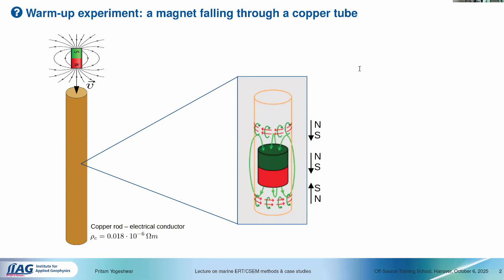So that is coupled to an electric field. Then along this ring current, you have again a magnetic field circulating around the ring current. And this magnetic field, if you look from the top, the direction of the field lines are like this, but the magnetic field lines of the permanent magnet are like this. And if you look down here, the magnetic field lines below from the ring current are reversed. So here, because it's north-south, north-south, it holds the magnet up, it pulls the magnet up, and down here it actually pushes the magnet up. So like this, it decelerates the magnet.